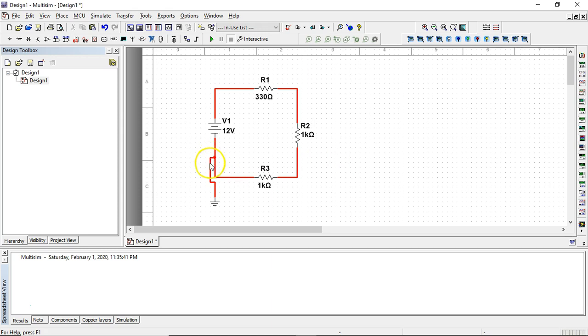Now say you placed your component there. You connected the wire from this component, the ground, to the circuit all the way up here, and you don't like that placement. Well, instead of deleting the wire, notice if I hover near the end of it, I get this option that sort of looks like an X with 2 lines coming off of it. That X with the 2 lines coming off of it allows me to change that connection point.